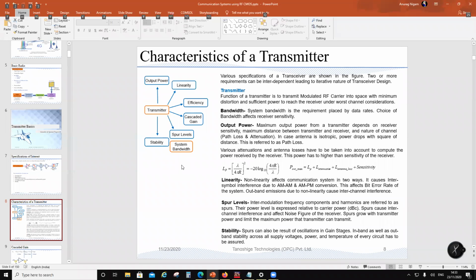Now, talking of certain systems, GSM is 2.5 watts or 3 watts. CDMA is going to be half a watt or quarter watt. If you go to Wi-Fi, we are talking about something like 19 dBm, 20 dBm, 21 dBm linear. So it depends on the system. They have been designed for certain range and so on. Again, it's a function of wavelength.